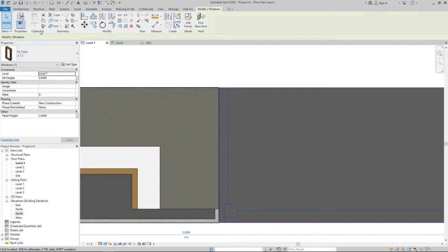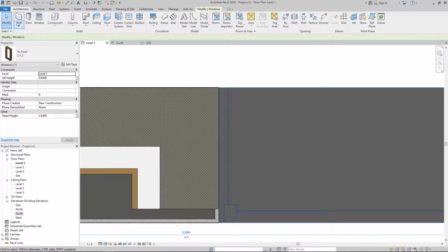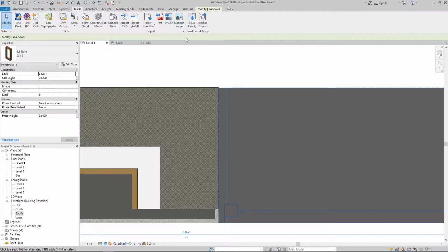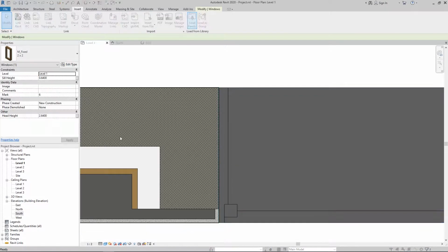properties. I'm going to close this. We're going to go to the next object. This component, we're going to talk about in the next video. I'm going to talk now about a column. Well, now before going on, I'm going to teach you how to load these families in case you want to load some of them. So I'm going to insert and load family.